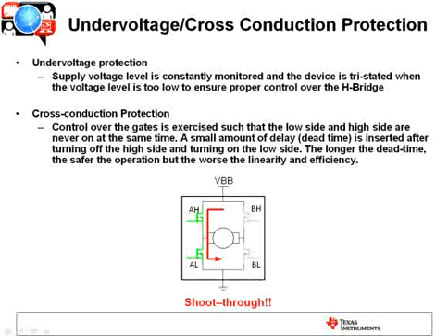Now, cross-conduction protection we talked about, that's really tied to the gate driver. That's ensuring that the high side and low side are never turned on simultaneously. And we mentioned earlier that this is accomplished by inserting a small amount of off time where the FETs are off. We call this the dead time. It's inserted right after turning the high side off, but before turning the opposite low side on, or the actual same low side on.